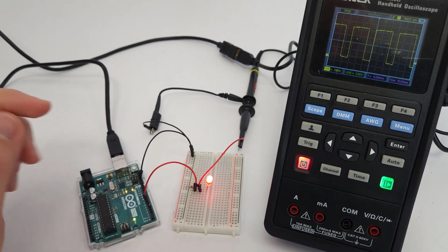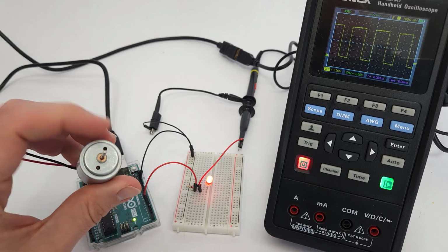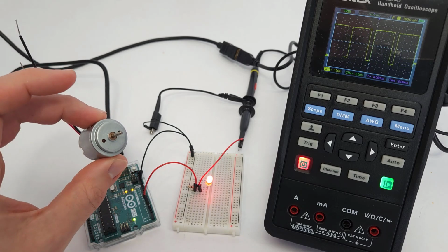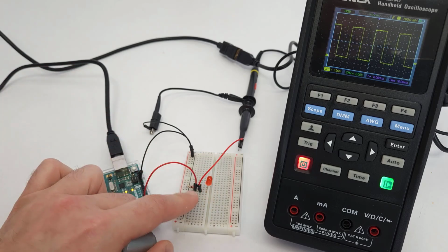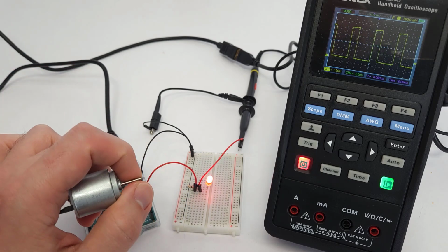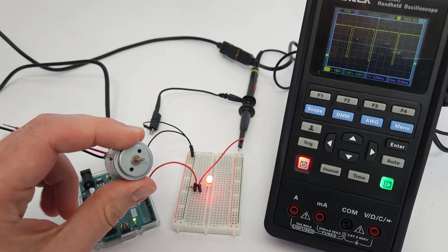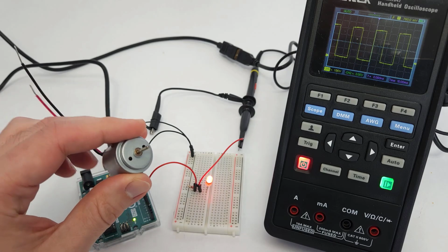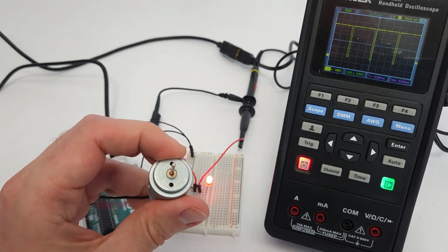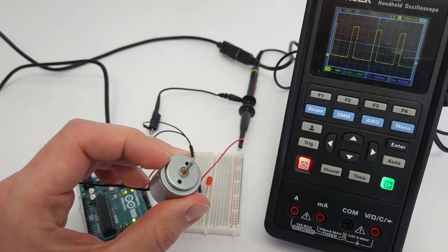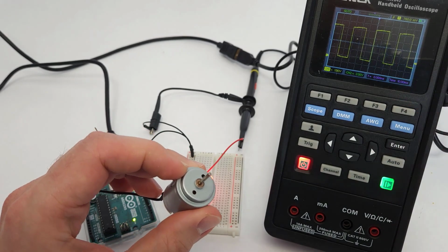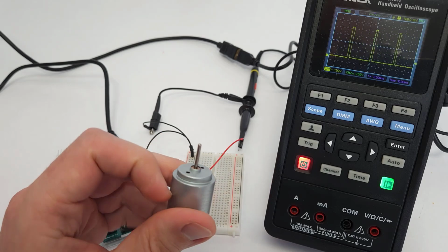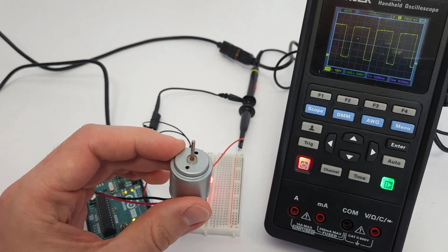Now, this is where you might need to play with the prescaler value depending on the physical system you are driving. For example, this could be different for a motor. For the LED, again, when the prescaler gets too big, we can see it flickering. For the motor, if the prescaler gets too big, you might actually start to see some oscillation in the velocity instead of a constant velocity. But for a motor, if the prescaler is too small, and if the driving frequency is too high, then you might also not get a response out of a motor, because the motor effectively acts like a low-pass filter.